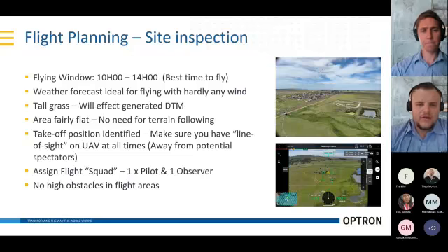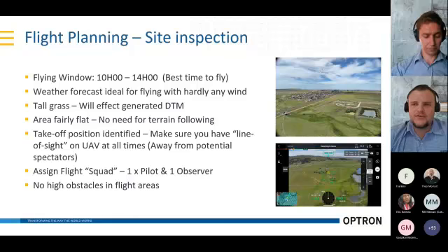Yes, so terrain following is quite effective. I've used it with the Matrice 300 RTK. We used it in George, where it was very mountainous terrain, and to do terrain following you just need to obtain a DSM, a digital surface model. You then pull it into your flight planning in the DJI planning software, Pilot, and then you can choose the height you stay above the terrain, so it actually follows the terrain as you go. Especially in George, where they are now farming up into the mountains because of space, that's a good application for it. It works very well.